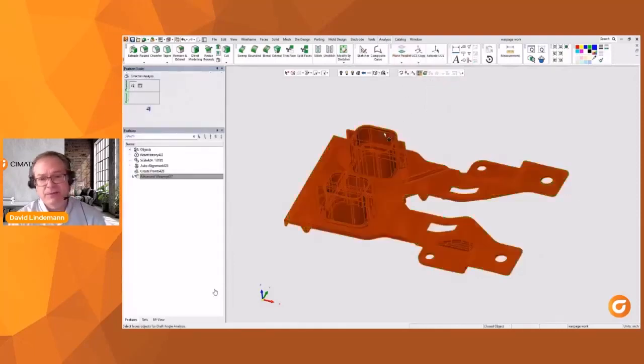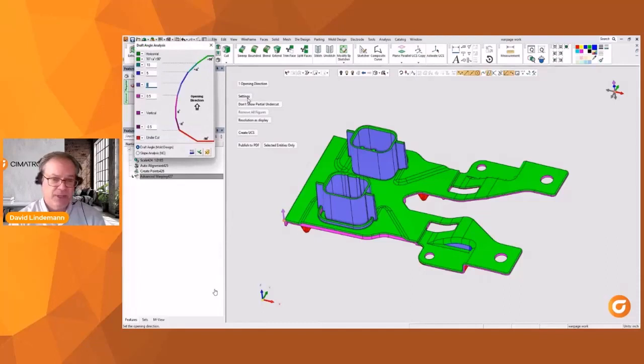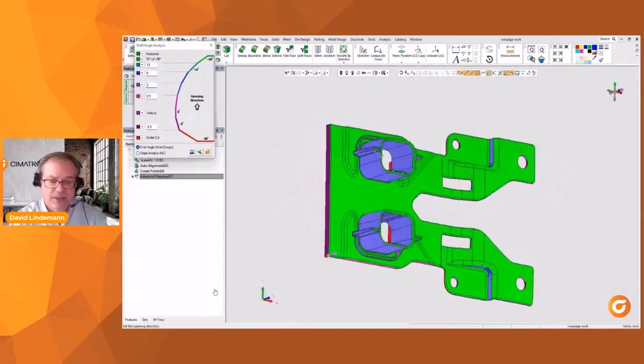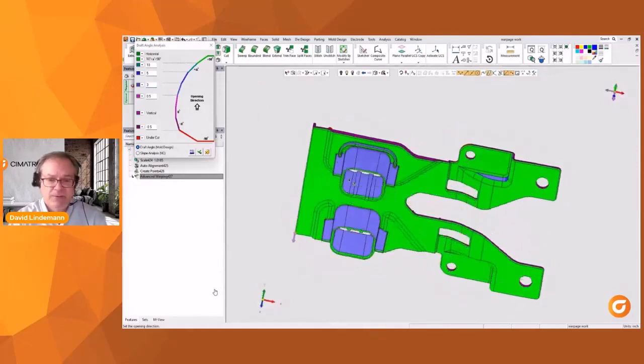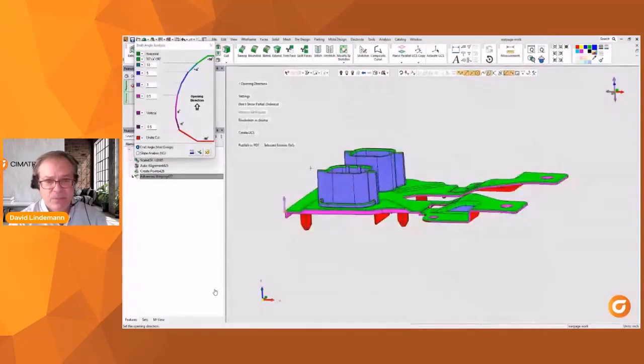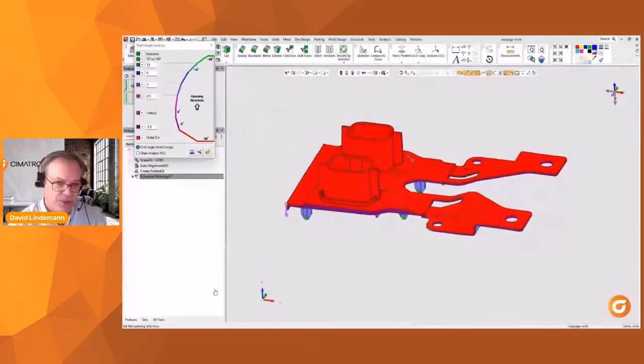First thing is I want to double check the draft conditions. I know the STL file had undercuts, but here when I look at this compensated part, again, based on the color ranges, the values I type in, I'm seeing as I move the tooltip around the different features that it's holding a positive direction. All right, so I've got a good draft angle. Even down here on the side, I've got 1/2 degree of draft working for me. And the direction it's reading it in is kind of that direction of that pink arrow that you see.